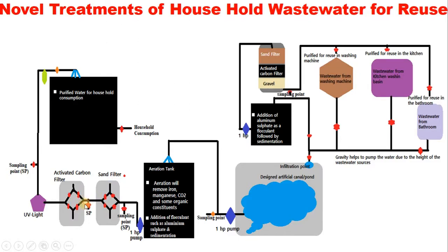You close these two valves, you open this valve, the debris will be pouring on the floor here. You will do it for a bit, for 5 to 10 minutes. The same thing is applicable to this place. You close this valve here, so the water coming here, instead of flowing normal, you will now close these two valves here. These two valves here will be closed. Then you open these two valves here.